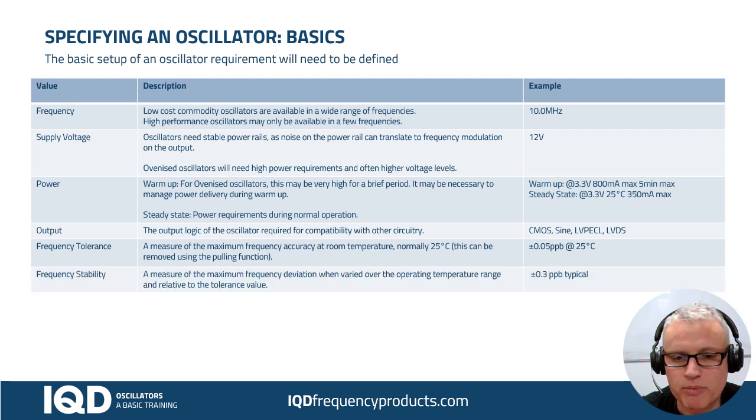The next parameter we might discuss is called frequency stability, and here we're talking about the change of frequency as caused by temperature. So now we're looking at that curve that we saw for the AT cut crystal and how that's going to behave. As I said, I can change that curve a little bit by changing the angle that we cut the quartz at, and I'm going to try and hit your requirements but I'm also going to try and hit your budget.